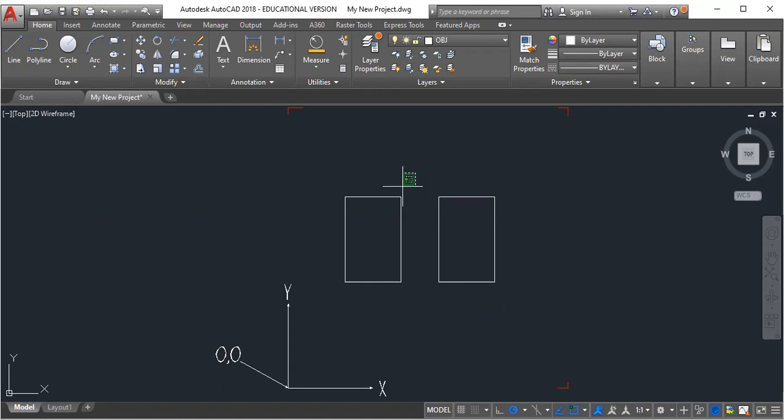So in this case, I'm just going to use my crossing window. I'm going to choose this rectangle and I'm going to join them. Enter. Now, when I roll over this one, it is one single object joined together. And this one now is all pieces parts, I can just the same way explode this one back to its parts. And I can come back and erase my right side lines and be done with it. So in this video, we talked about two different ways to draw rectangles, how to explode a rectangle, and how to join various parts together.